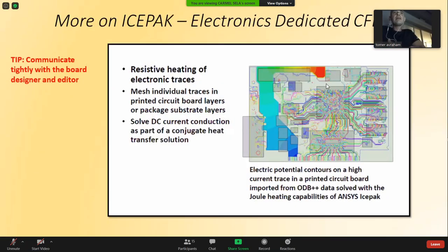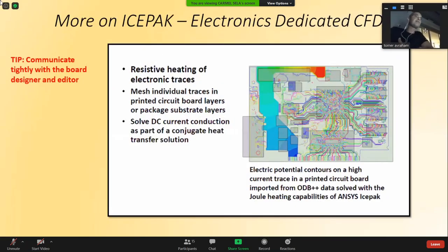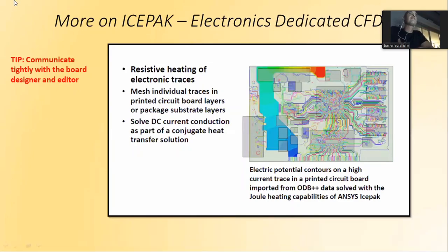The other thing that you can do, now this is on iSpec, but you can also do it on FlowTherm. I think FlowTherm is a lot better for this even. You can read an IDX file. It's a file from the board designer himself, with all the traces and everything. And it can give you the ODB++ file or any kind of board design file. It could give you a full picture if you want.